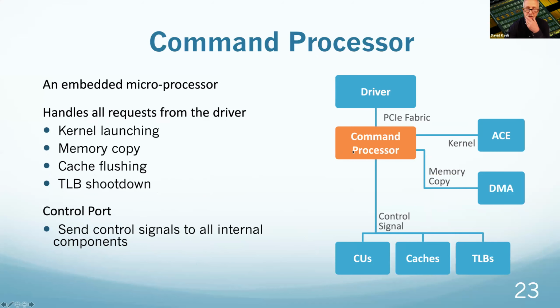From the driver, we send these to the command processor, which is going to then send them to the ACE units or do DMA operations or other control signals. So it handles all requests. It handles kernel launching, memory copies, cache flushing, and TLB shootdowns. There's a control port to send control signals to all the internal components. So again, a very rich component, the command processor.